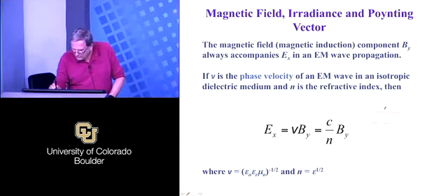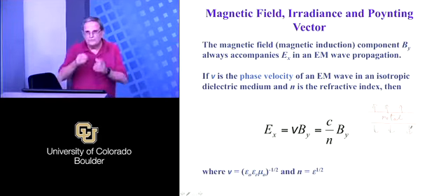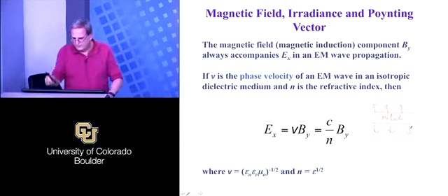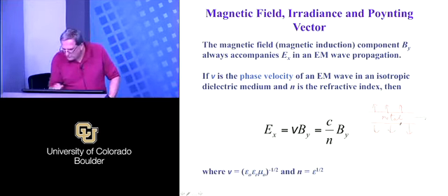he was the one who said, well, look, on the outside of the metal, let's say this is the metal conductor, on the outside of the metal, the electric field is pointing out. So the electric field kind of looks like a porcupine. He said, well, at some given moment, the current's going that way, so there's an H field going this way. Let's call that H_phi, call that E_r, and let's call that S_z, the Poynting vector along the z direction.